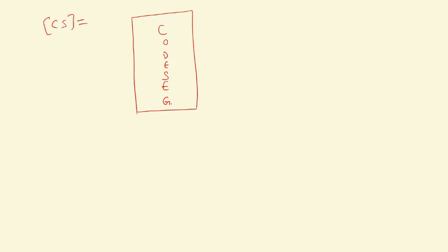Suppose the microprocessor is executing the main program. Suppose this is the code segment, and the base value of the code segment is held by the code segment register, say 2000H. Somewhere at this position there will be a CALL instruction with address 500H, and the offset at which this call is stored is held by IP, which will be 100H.